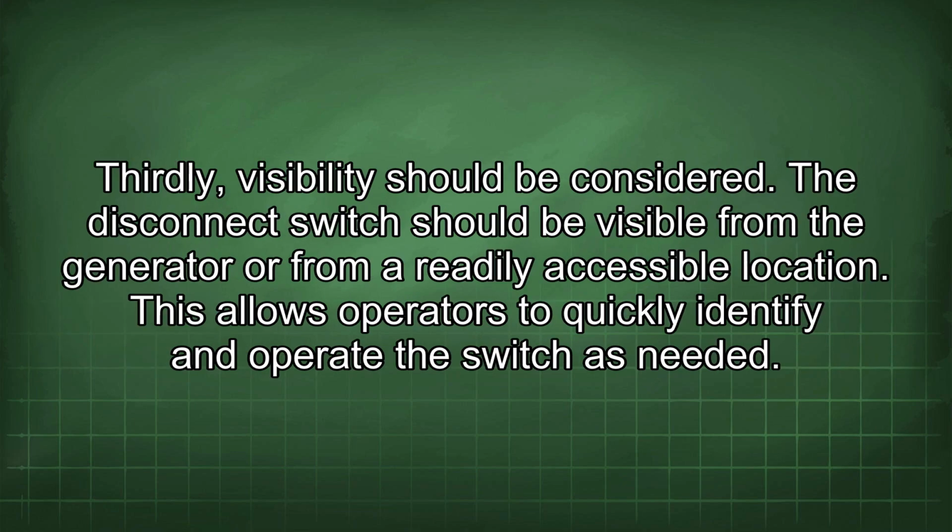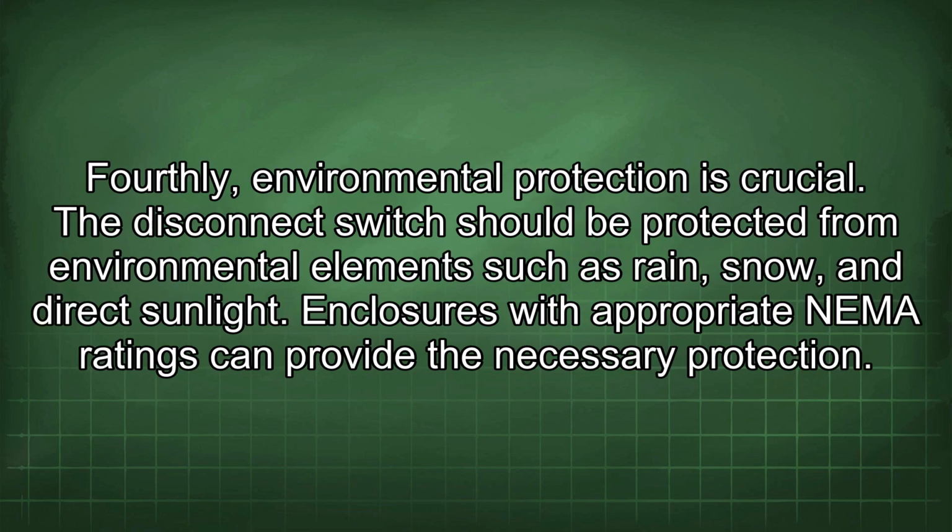Thirdly, visibility should be considered. The disconnect switch should be visible from the generator or from a readily accessible location. This allows operators to quickly identify and operate the switch as needed. Fourthly, environmental protection is crucial. The disconnect switch should be protected from environmental elements such as rain, snow, and direct sunlight. Enclosures with appropriate NEMA ratings can provide the necessary protection.